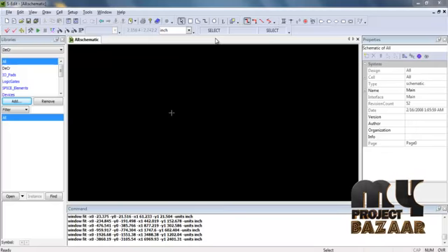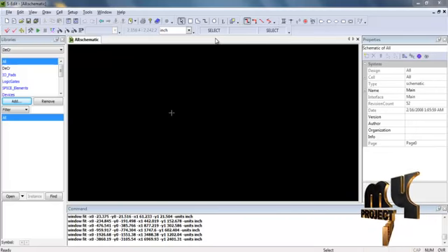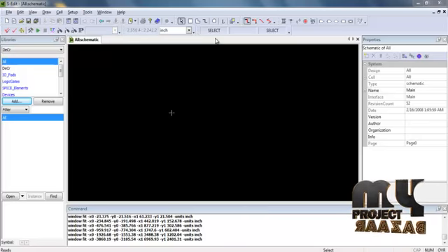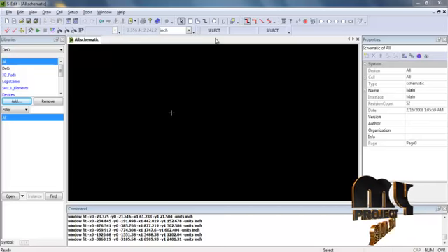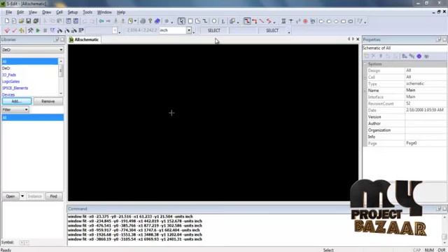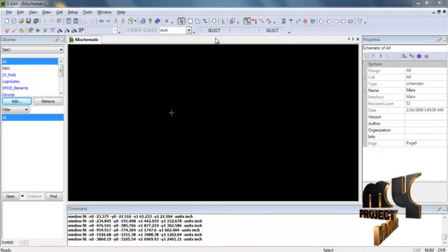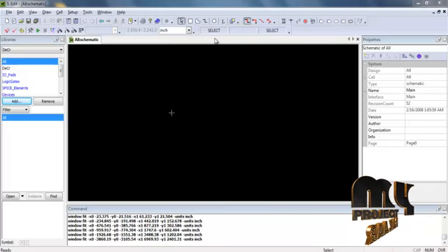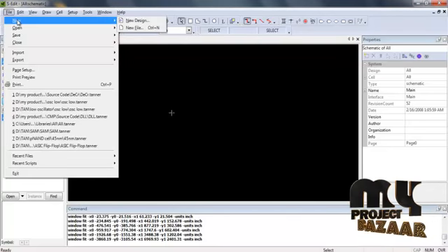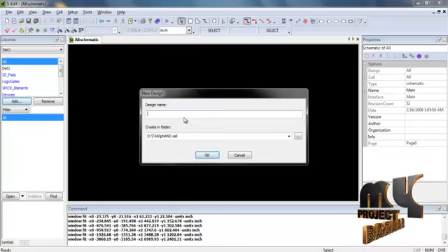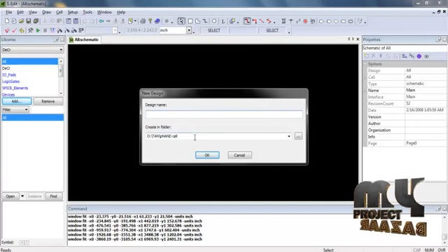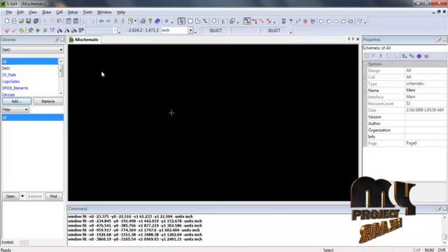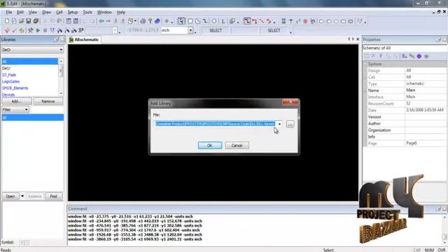Now we are going to discuss the running procedure of our product. Our product can be implemented by using the Tanner EDA tool 13.0 version. Now we double click to open the tool window and create a new design using the File menu. File, New Design, to create a new design with the desired name in the desired path. After creating a new design, add the library files from the Add option, choose the desired path of the library file, and click OK.